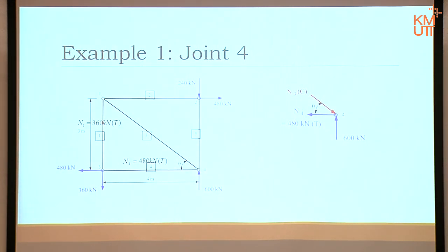Okay? In this case, it means that if we calculate N3 positive, N3 is not tension, N3 must be compression, meaning we put in the right direction. If it's negative, it becomes tension, right? Again, it always goes against your assumption. Okay? Then next is that one.